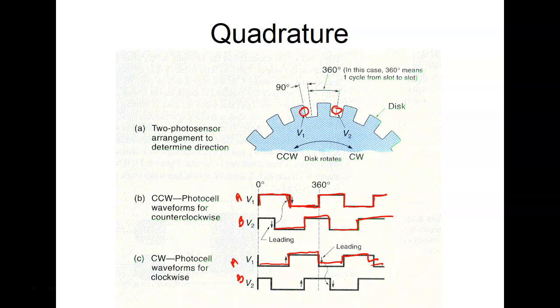But the batteries on the ABB, you have to buy from them. Those are like $240 a piece. So on our robots, we don't change those batteries out until the robot doesn't work, and then we just remaster it and let them use it until we buy the batteries. And most companies can't afford to master the robot. It takes a little while to master it, and it depends on how accurate you want it.